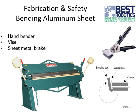If you see that picture down at the bottom right, that gives you an idea of how you want to situate everything. You want flat surfaces on both sides of the bend, to help you bend things and keep it straight where it's supposed to be straight, and just bend around the part that you want.